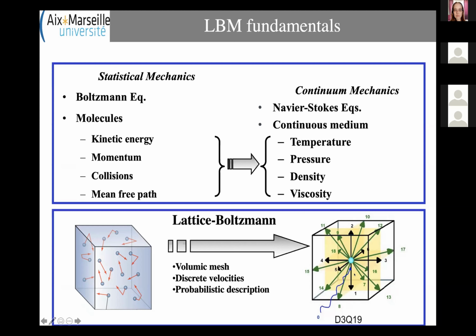The Lattice-Boltzmann approach is such a method because we are decreasing the dimensionality of the problem by defining a given finite number of discrete velocities, meaning that we are not using a grid in the velocity space. We define a set of discrete velocities, not fully arbitrary; of course, it has to be done in a smart way to get an efficient method.